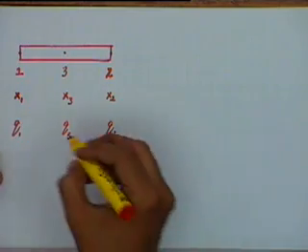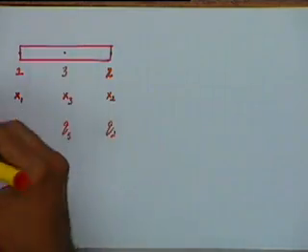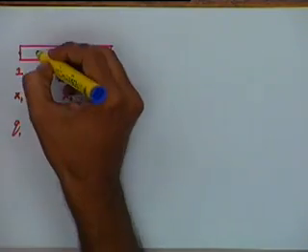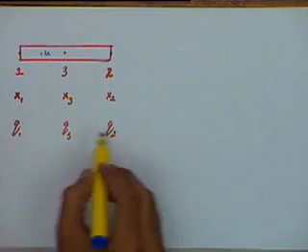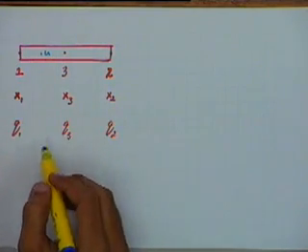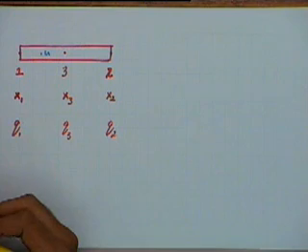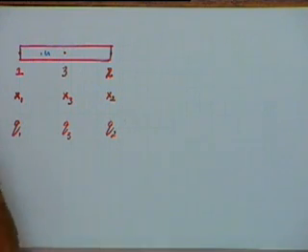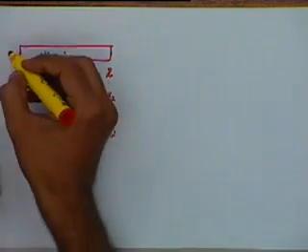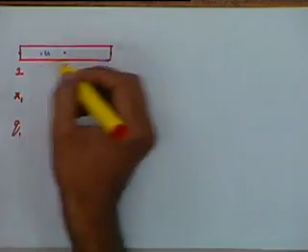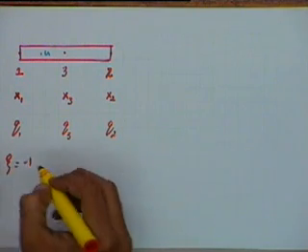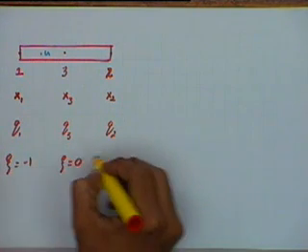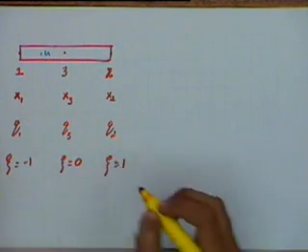Again, if I want to find out u at any arbitrary point, that u will be a function of q1, q2 and q3, but now we will do a quadratic interpolation instead of doing a linear interpolation. We will again define a local coordinate system, zeta, and zeta at this point is -1, zeta here will be 0 and zeta here will be equal to 1.